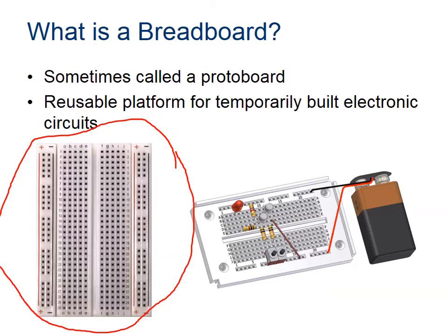A breadboard also allows us to simulate a circuit, so it allows us to observe how and if the circuit actually even works. It's really a test bed for us. It gives designers the ability to change components during development and testing. In other words, you can swap out resistors or capacitors and play around with some of the values of those things. And finally, it allows us to modify a circuit to easily measure voltage or current or resistance.